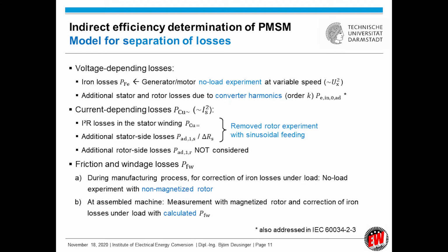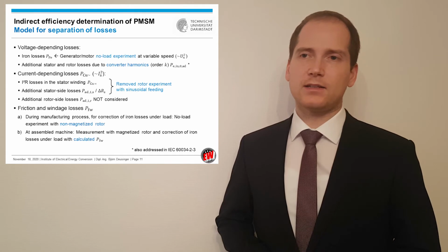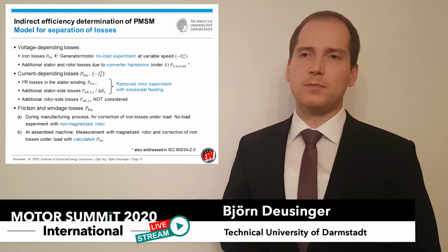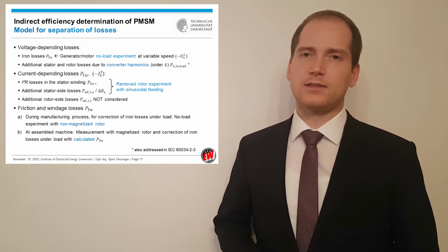The third component are the mechanical, friction and windage losses. They occur already at no load. In order to perform an accurate recalculation of the iron losses, the mechanical losses are either measured with a non-magnetized rotor or calculated, if this is not possible.